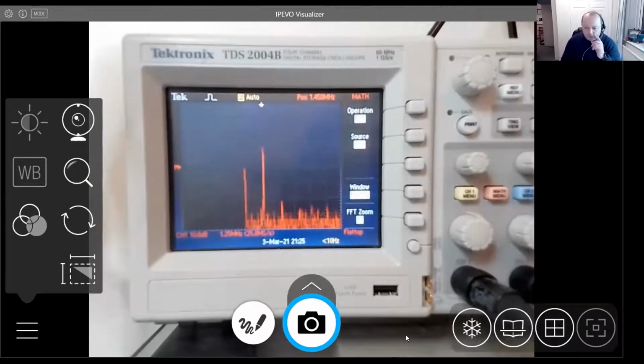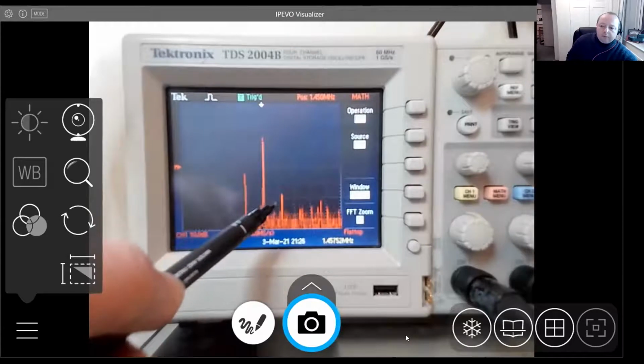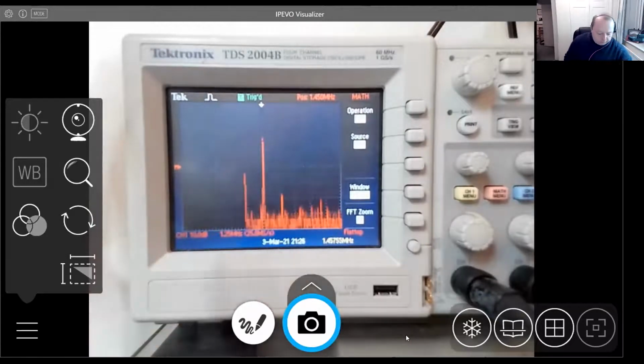That red line in the middle is the frequency of the sine wave going into our op amp. But if I increase the amplitude, so it starts to clip, we should, and of course it never works when I do my demo, usually you can see next to it these other harmonics start to pop up. I think maybe if I wind it down, it might disappear reasonably. There you go. It's almost disappearing.